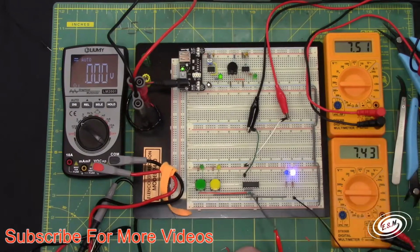So if you subtract the two, because the chip is driving the LED, really 0.05 milliamps is what the chip is using. The chip is using only 0.05 milliamps itself, the quiescent current of the chip.